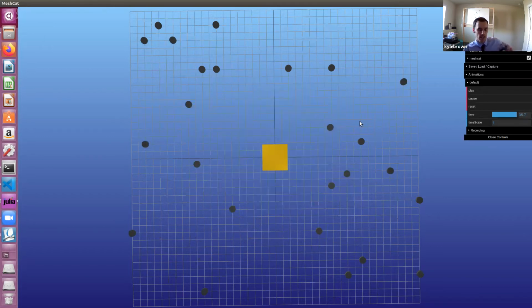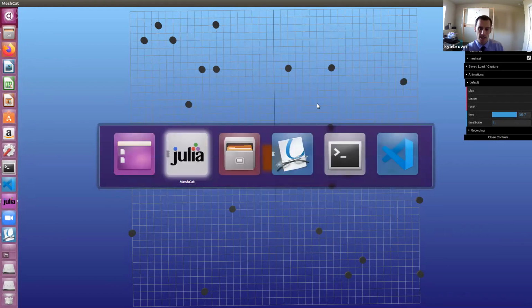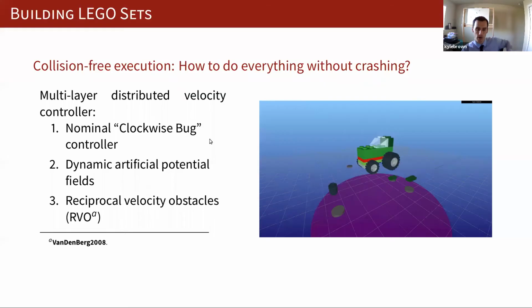So basically, as a high priority agent is moving toward its goal location, this has the effect of politely asking the other agents to move out of the way. And I found that this is very effective in reducing and in fact removing the gridlock that can occur if there's no extra part of this controller to encourage agents to get out of each other's way.